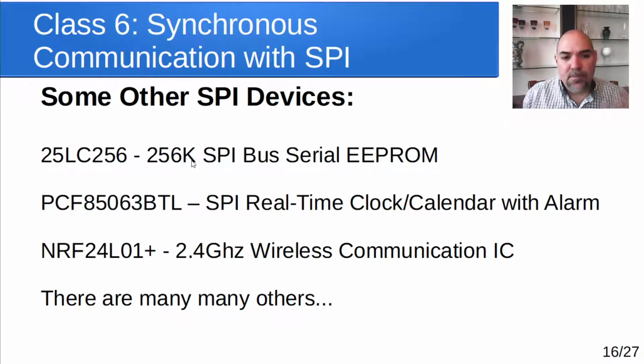So to connect this, you just connect, and if you want some kind of storage on your microcontroller or on your embedded system you're designing, you drop one of these EEPROMs onto an SPI bus, and you can send messages to store things, send other messages to pull data back out of it. Very easy to use, very cool, and very easy to interface. You just got the four wires: slave select, MOSI, MISO, and the clock.